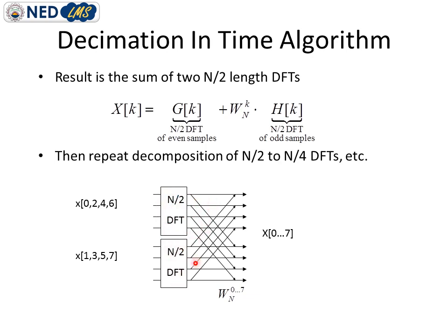G of k is the output of the first DFT block and H of k is the output of the second DFT block, and we combine these two results in a special manner to get the desired output, which is the frequency domain view of that signal. You can notice the spatial structure these lines are forming. Because of this structure, this pattern is known as the butterfly structure, because of this very specific pattern of FFT.